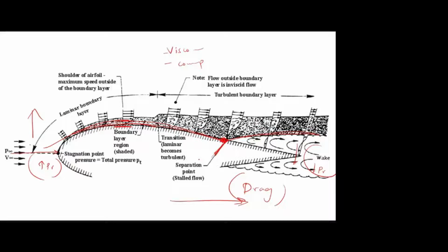If you are reading many research journals, you may come across the term delaying the flow separation. Delaying means we are moving this separation point rearward. Instead of from here, if you move it to here, then the flow will be attached up to this point. Then from here only it will separate. Now you see only this much wake we have. So the wake is reduced.